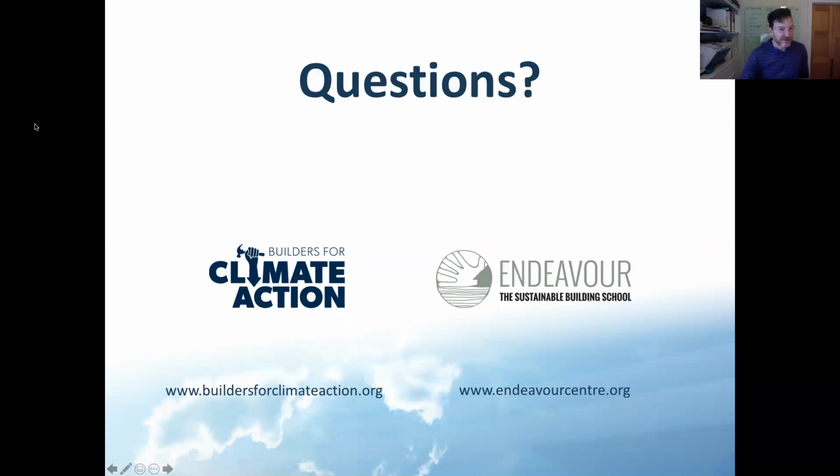James asks, with reference to hemp, how could hemp help with overall embodied carbon? Well, hemp is another plant-based material. Depending where it's grown, it's between 40 and 50% carbon by weight. Our calculator includes both hempcrete and hemp bat insulation, so when that comes out, you'll be able to see directly how those numbers compare. Hemp is no better or worse really than any other plant-based material in terms of its carbon content. So again, a lot depends on other factors.